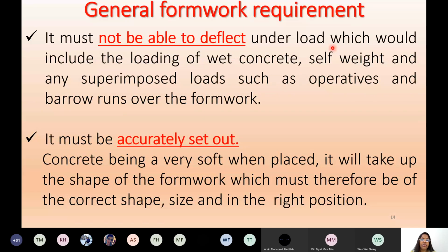Second common mistake, common problem will be deflection, because you're going higher and higher, isn't it? It's a temporary structure, you're not really digging a foundation to hold these structures, right? It's hardly drilled, just drilled inside, or using some plates and screwing, or small welding. It will be done, plate to the ground, supported to the ground. So it is all by self-weight. It's standing by its own self-weight. So you need to take care of the deflection.